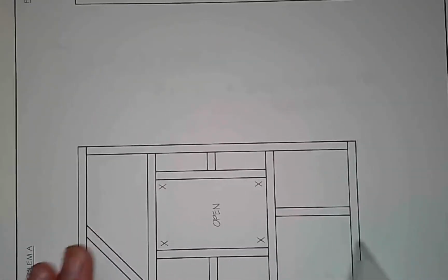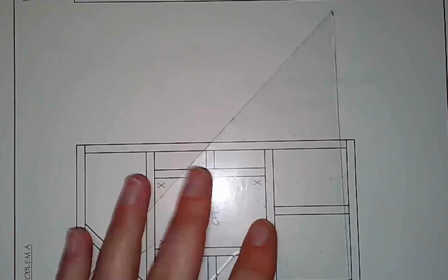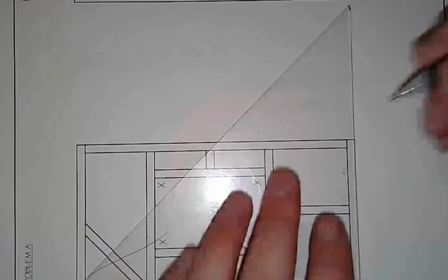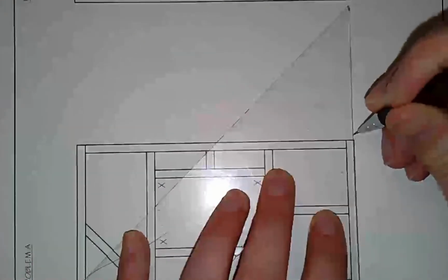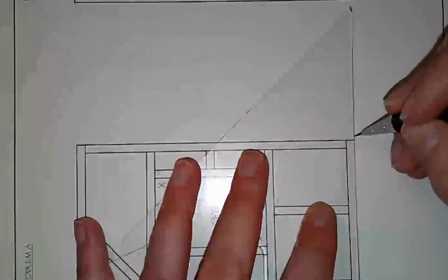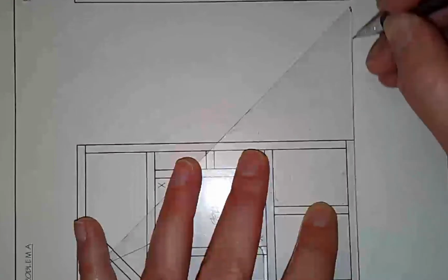The furthest distance from the drafting is going to be the complete length of the side. So in this case, I would do a dimension line, and I'm pulling it from about 1/8 of an inch outside of the object because I don't want to intersect the object if I don't have to. And then I'm pulling it straight up away. So that's the outside-most line in terms of that edge.